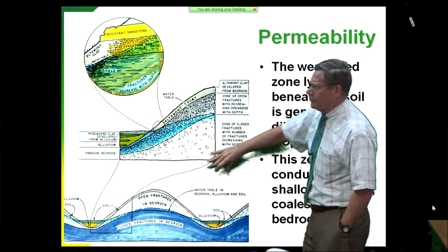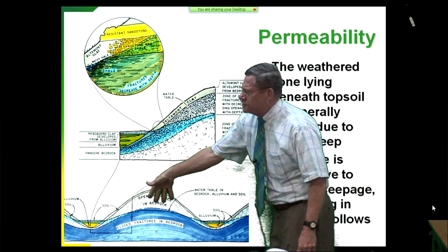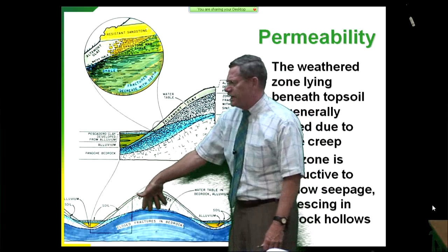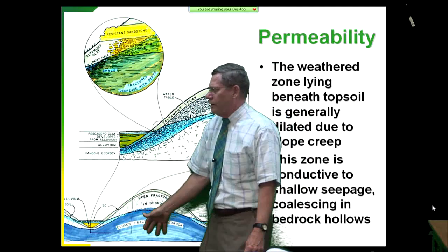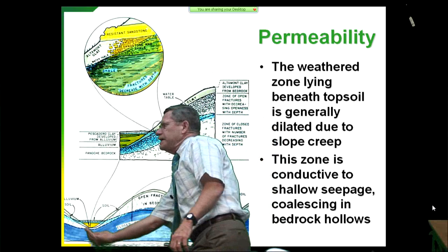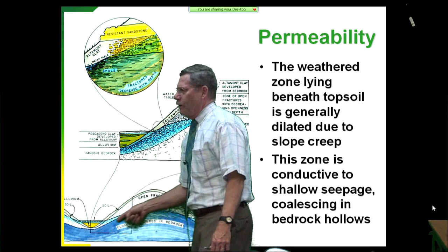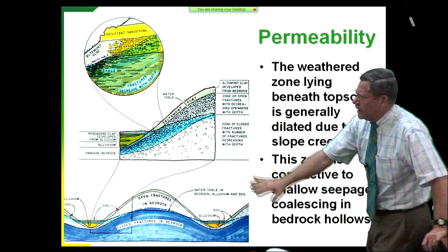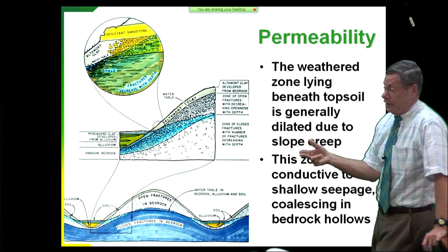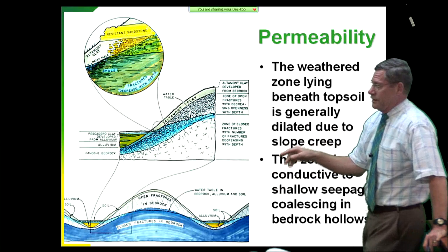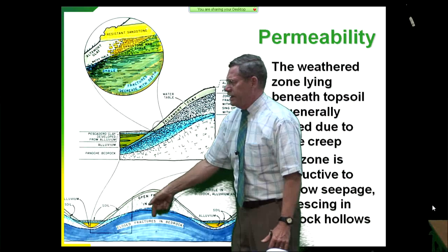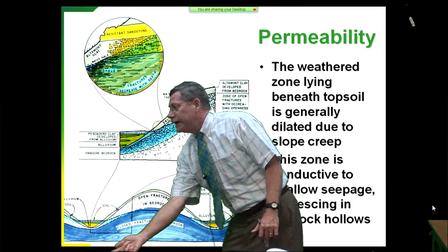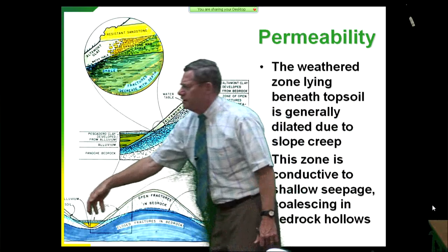So I've got water that's percolating into open fractures right here, and then it's moving pretty rapidly one way or another. Now, I have increased head right here. So this actually pushes this water like this, and it gets down here first, actually before that water gets there. So you do have to think about it three-dimensionally. Now, in school, we always draw two-dimensional pictures like this. But in the real world, it's very three-dimensional. So when I'm pushing water down right here, it's not moving in this plane. It's actually moving towards you. So it's going that way, but it's also going downstream because of the influence of the other water right here